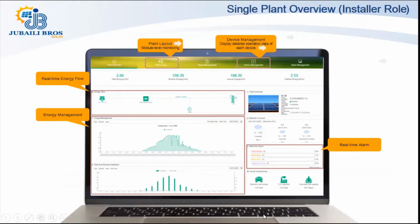Single plant overview, installer role. If you are going to view a PV plant as an installer role, this is how it will look. Under the plant view, you will have the basic diagram of your PV plant in real time, which will show you the real-time energy flow, whether your PV plant is generating, and if it is going towards the load or towards the grid. If you have a power meter, it will also show you exactly how much power is going to your load from the grid side and how much power is coming from your solar side.